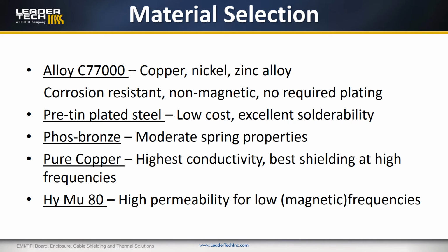When we're designing an EMI shield, the first aspect that you look at is what type of material you're going to make the shield out of. So you have to ask yourself, how is the shield going to be used? Will it be in a corrosive environment, outside, in a vehicle maybe, or is it going to be indoors in a protected environment? So we have multiple options of material.